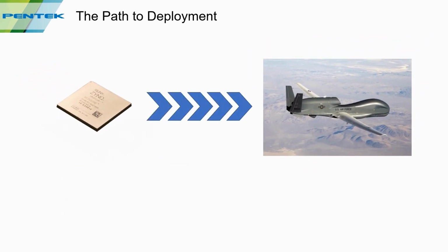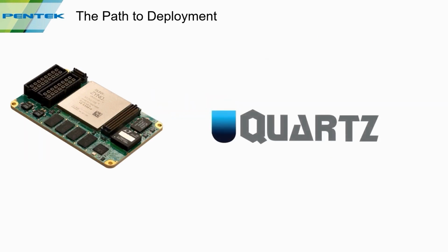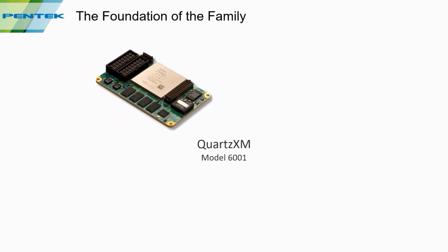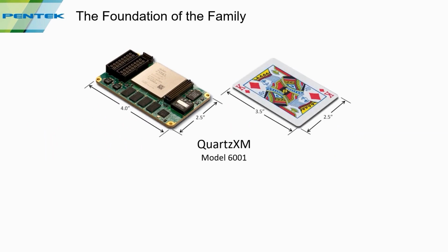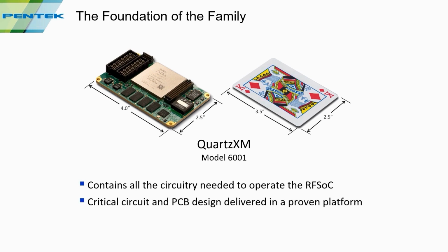And to answer that, Pentek has our Quartz family of products. Now these are based on a small system on module, the Quartz XM. And to give you some idea of its size, it's 4 inches by 2.5 inches, and I'm comparing it to just a standard playing card to give you some perspective. Now the whole idea behind the Quartz XM is that it contains all the circuitry needed to operate the RFSoC. All the critical circuit design and PCB design is in this SOM, or system on module, and it's delivered in a proven platform. And it's designed to operate on carriers, but there's a wide range of different carriers available, including custom carriers that you can design on your own.